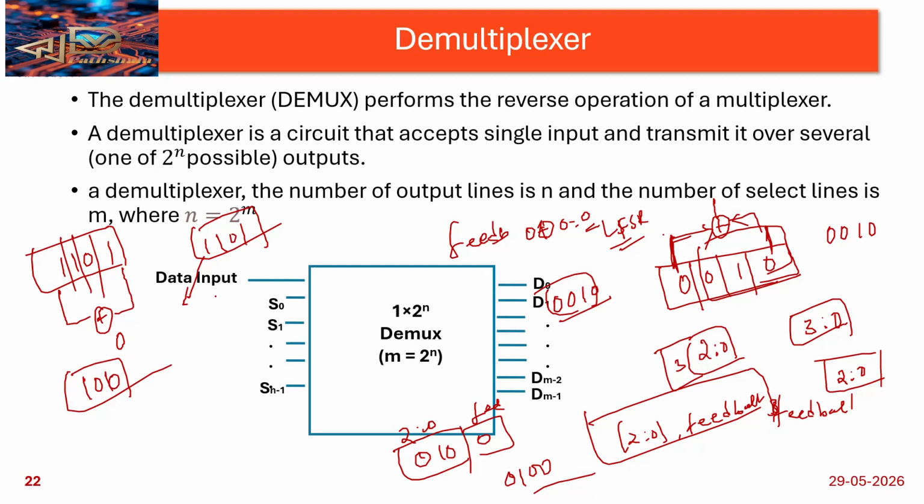Do one left shift operation for this. What is the output? This 1 is going out, 1 0 1 is coming here, then 0 will be placed here. Then the same thing will be operating. It's like a left shift operation, but every time random patterns will be generated.